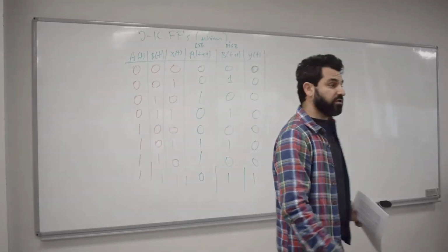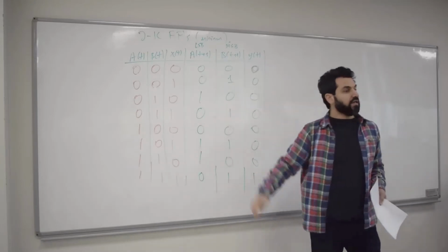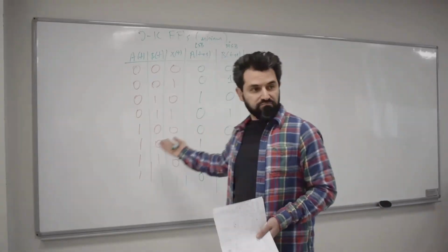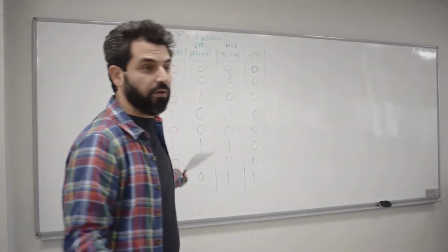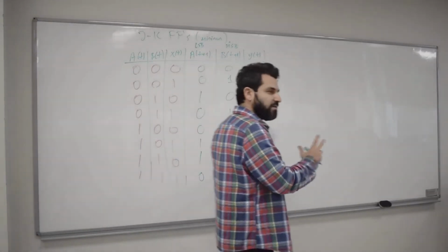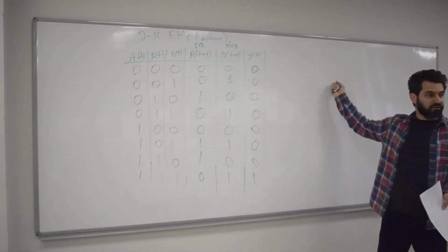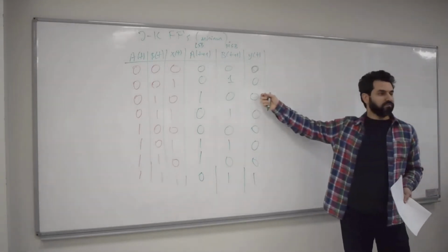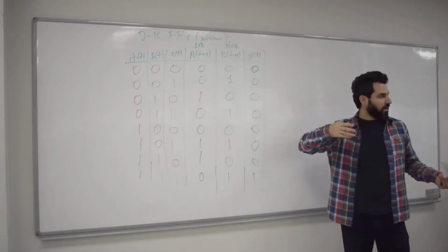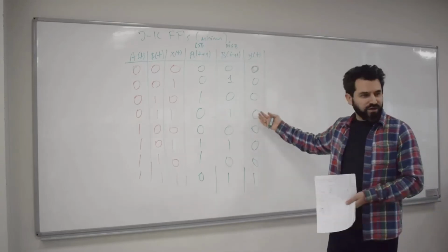Okay? You see there's a one-to-one relationship between the state table and the state diagram. Okay, but this looks much cleaner because that's what we're familiar with using the truth tables, right? So, this is the next phase. So what's the next phase from here? Do you remember? What do we do now? Karnaugh maps. Absolutely. State equations. In order to find state equations, you need to find the Karnaugh maps.